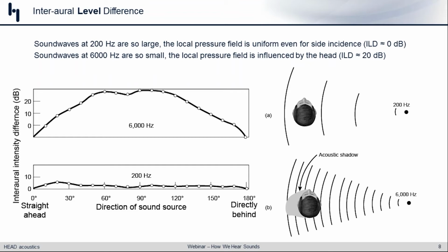Rather than just maybe muting the conversation a bit and completely overriding with binaural stimulation, why not have the conversational partner rotate their virtual sound location off axis and then maybe rotate in the direction of the navigation prompt, and then once the prompt is done, you can rotate the conversational partner back to the front. Little things like that you can play with to enhance the user experience of something like a binaural product like that.